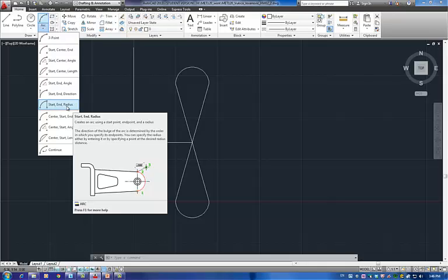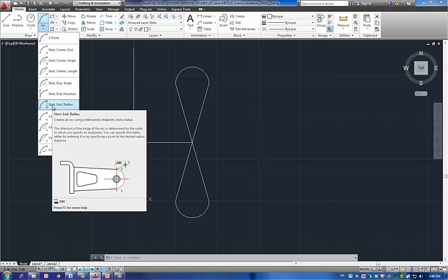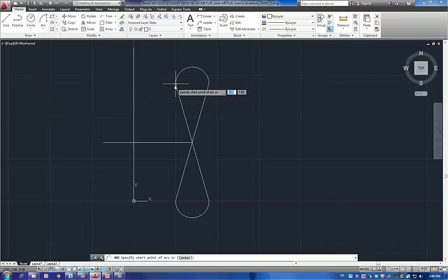So okay, and now I will create an arc, and I will use the option center, start, radius. In this way you should use the counterclockwise option. So first I will select the one with quadrant here on the top, and the second one will be the one in intersection, start and radius, and then I will type radius of 4. So start is this one, the end is intersection, and then the radius is 4.